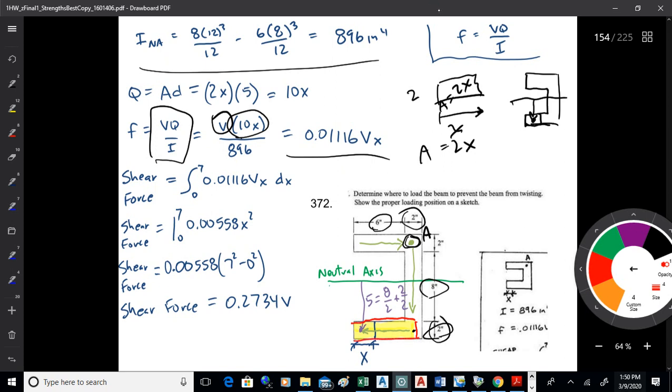So we're going to assume that that flange is 6 plus half of 2. It's 7 inches. We're kind of taking this area, which is kind of ambiguous. Half of it is split between the web and the flange. So I'm going to give half of it to the flange and half of it to the web. I think that's really about as deeply as that's thought out, okay? I've not seen anything to indicate otherwise in the reading I've done on this, okay? So we just go from 0 to 7 with the integral.